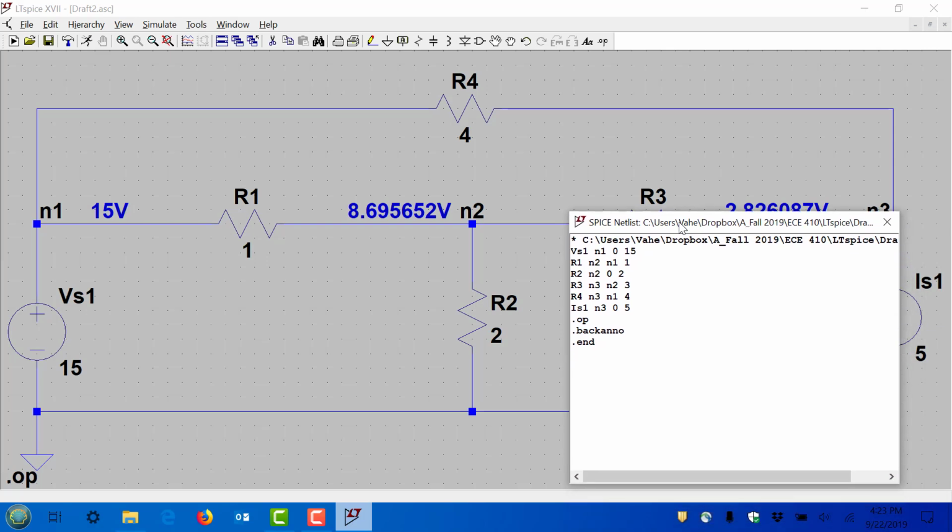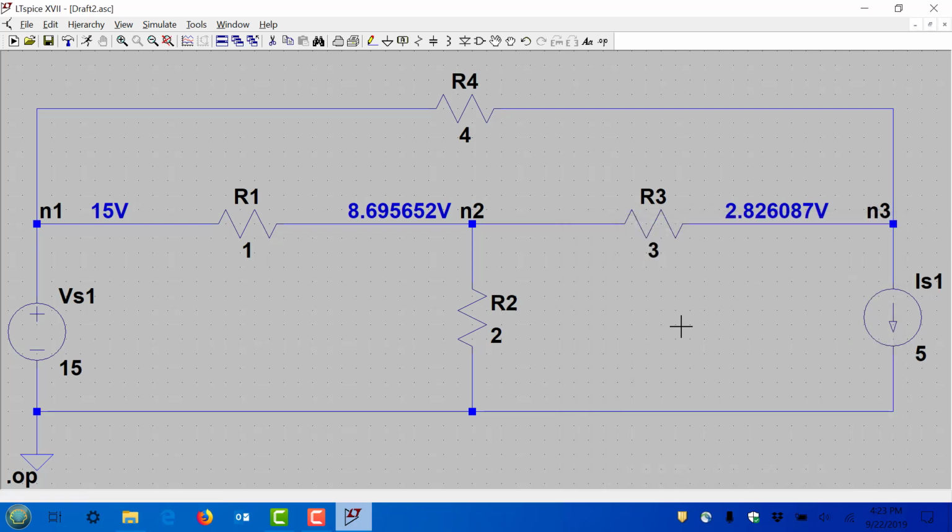All I'm telling you to do is, if you examine the netlist, you will get this information. And just remember, if you say I(R1) or I(R2), I(R3), right? In LTspice, if you see something like that, it's giving you the current going from the first listed node to the second listed node in this netlist. Okay? Or just realize that practically speaking, of course, if this side is higher than that side, positive current is going to go from left to right. I mean, that's obvious, right? That's obvious. But I just don't want you to be confused if you see something else on your information.